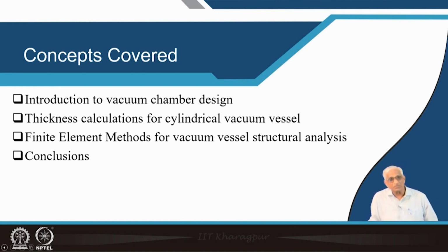So that thickness calculation depends on ASME codes, which are internationally accepted, and we will take up some examples and try to make some calculations so that, with respect to thickness, you get some ideas about finalizing a chamber design, particularly those people who have never handled any big chambers. You will get some idea how to proceed further.